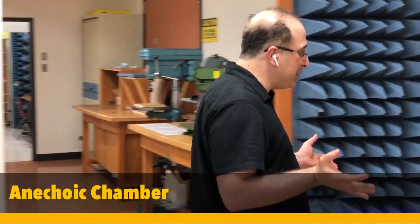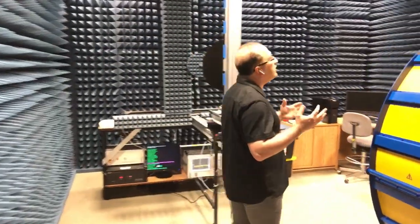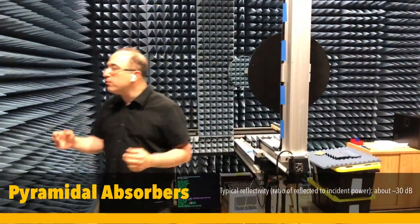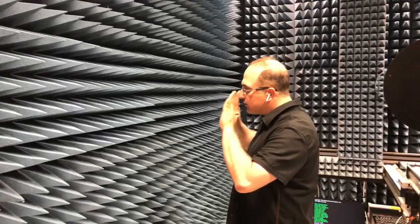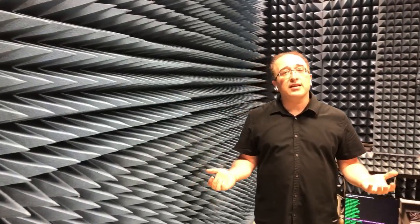Now, I'm going to show you one anechoic chamber that we have in the antenna lab. If you come to this room, you're going to see that all the walls are covered by pyramidal absorber, or radio frequency absorbing material, or RAM. They essentially absorb electromagnetic energy. These are ideal for normal incidence. When the electromagnetic waves come like this, the reflection is very minimal, so you can assume that you are operating in free space.